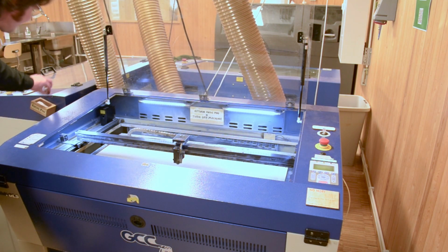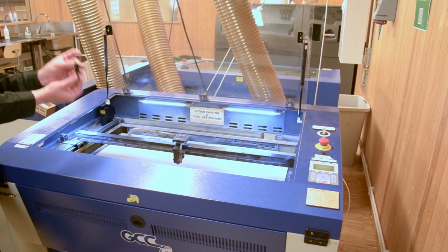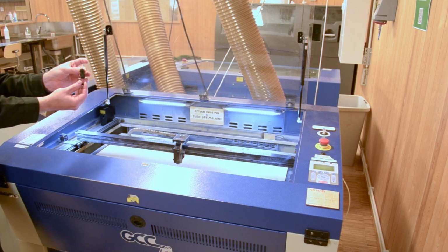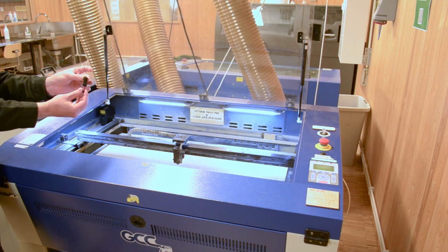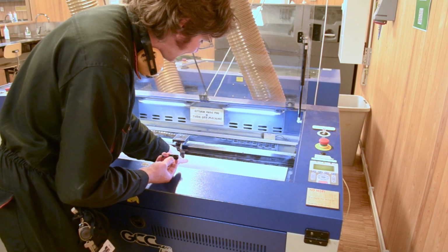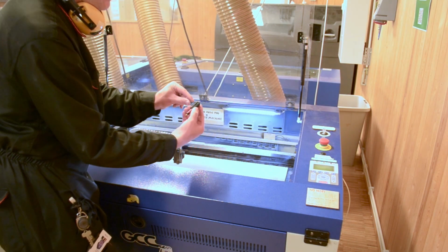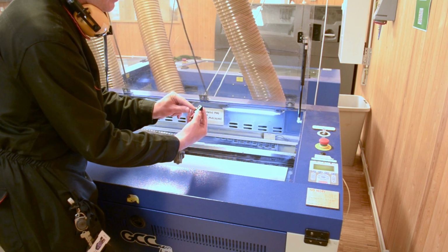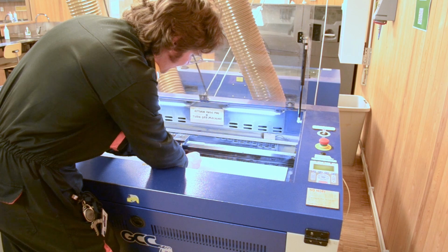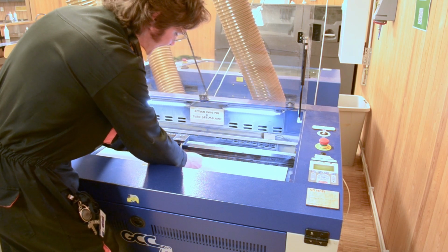Take up the autofocus pin. This is a piece of delicate, expensive hardware that is very easy to damage, so make sure that you carefully handle it. Use the 2 guidance pins on the laser cutter head to carefully align the autofocus pin onto the laser cutter head. Gently push it to position.